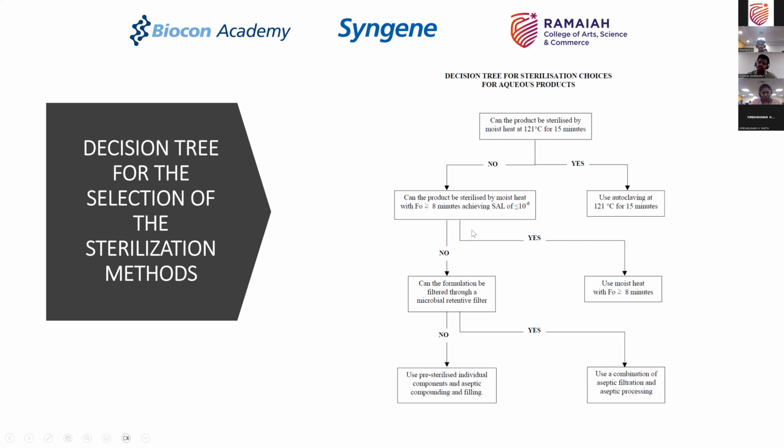The condition they are putting is that for a reasonable kill rate, if your F0 value is greater than or equal to 8 minutes and is achieving an SAL of less than 10 to the power of minus 6 within those 8 minutes, then you can still, by changing the condition, achieve moist heat as a terminal sterilization technique. Clear? Yes, sir. Okay.